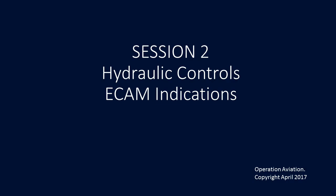Your RAT OUT message appears in green when the RAT is not fully stowed in flight, or the RAT OUT message appears in amber on the ground, just before takeoff power application, in the event that the RAT is not fully stowed. So we can just kind of get a feel for that. Again, looking at the diagram gives you a better orientation as you continue to review that.